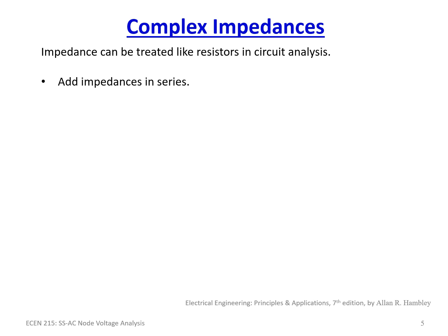So again, for review, impedances can be treated like resistors. If you have all of these impedances figured out, you can add them together in series, just like you would with resistors. So if I had a capacitor, an inductor, and a resistor all in series, and I computed their complex impedances, J omega L, minus J 1 over omega C for the capacitor, and R for the resistor, you can add it all up and you would get a complex number that represents the equivalent impedance.